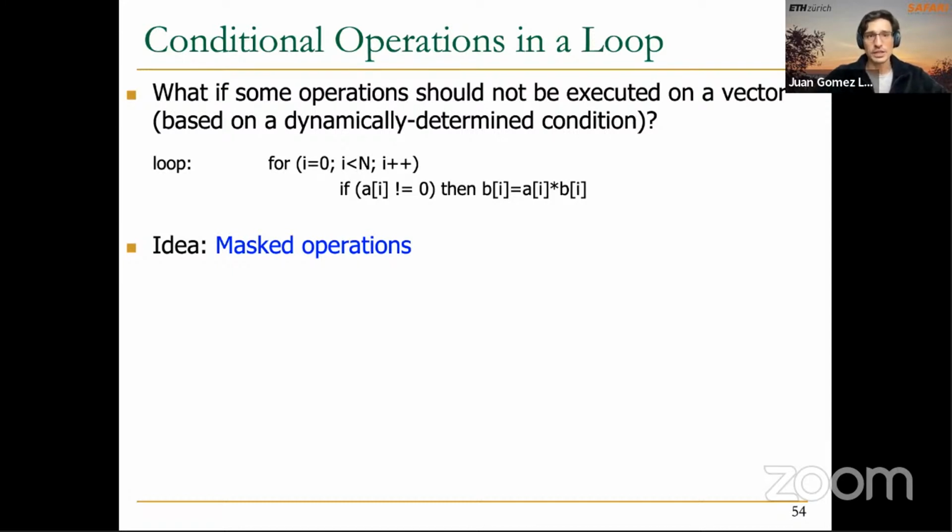But when it comes to accessing the DRAM memory, and you know that DRAM is also a banked memory, it's more complex than that. Normally these days, they are using hash functions in order to calculate what's the physical destination. And that's also one of the potential solutions that I'm going to mention in 3 or 4 slides. Okay, I can wait 3 or 4 slides then. Yes. Thank you. We will talk about that more, don't worry.